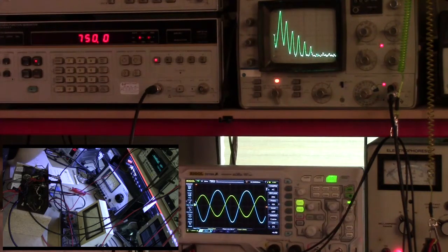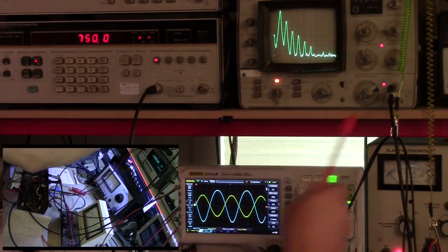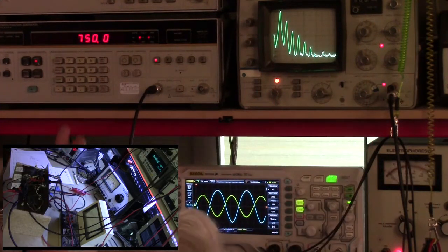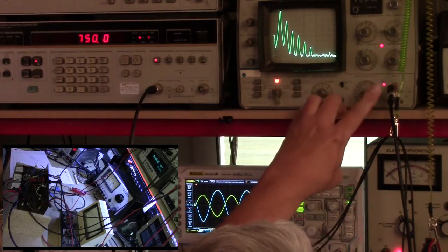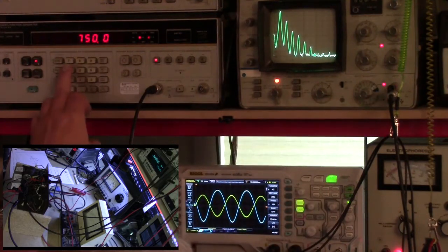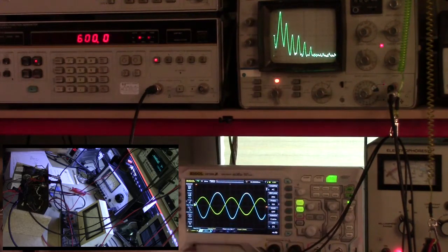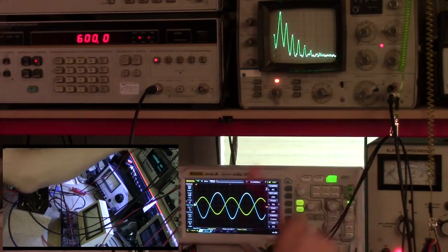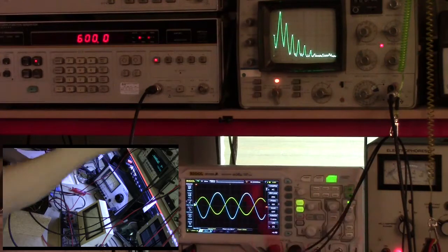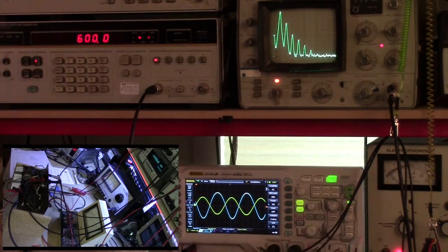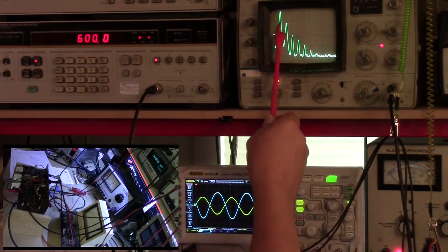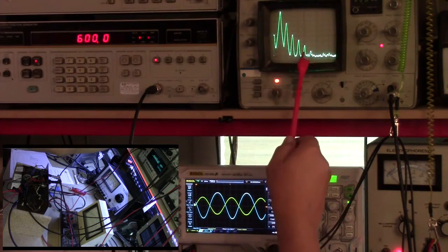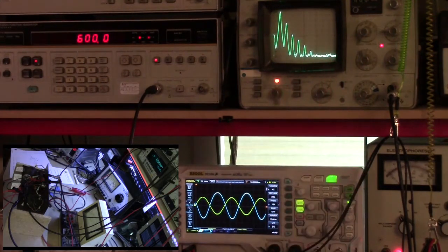Can't even do that. All right, so let's keep going down, because I think the measurement we took at 750 was wrong. We are overdriving the input stage, and the spectrum analyzer is going to show you the distortion from the input stage here. I think all we're going to be able to put in here is 600 millivolts. This spectrum analyzer won't take more than 100 volt input. Even at 600 millivolts, you can see our fundamental, second, third, fourth, fifth, and sixth, and it's fairly distorted, even though the waveform on the scope looks okay.